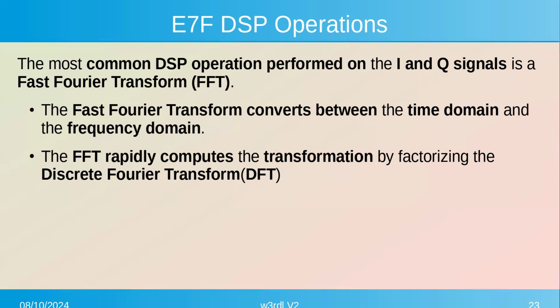And you see this spectrum. That's how on the newer radios, if they have a waterfall, the waterfall is the result of an FFT on the signals, on the whole bandwidth that you're seeing. So every one of those little spikes that you see is the result of a fast Fourier transform. And then in time, you're just doing those samples and building the waterfall.